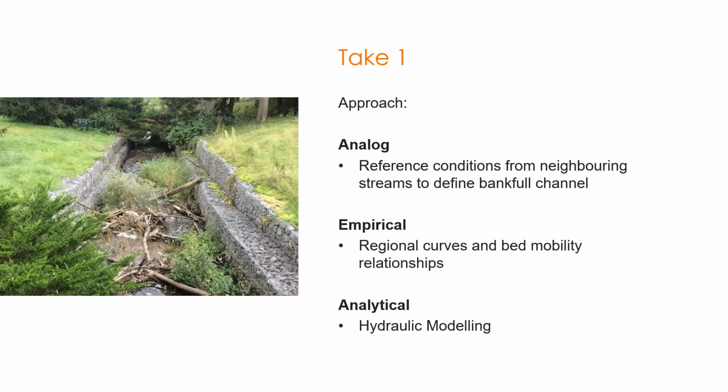In terms of an empirical approach, we evaluated some of our dependent variables using regional curves. We also used a series of empirical bed mobility relationships to size some stone for this water course, since we know that the upstream area is very urbanized and our bed load can be expected to be pretty insignificant. And lastly, we followed up with putting our design into a hydraulic model in order to evaluate flood elevations, velocities, and specifically in this case, some shear stress.